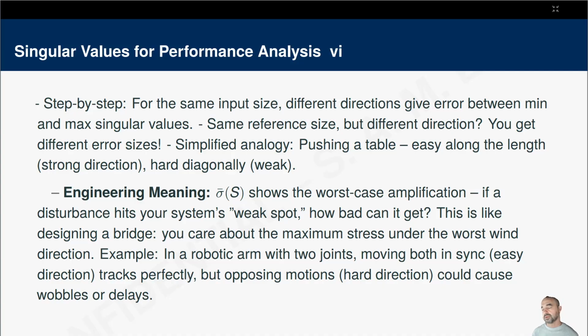In other words, think about it this way. If I consider maximum stress only on the nicest wind direction, the wind direction that is inherently gentle, rather than the one that creates maximum stress among all wind directions, I haven't really designed considering acceptable safety margins and safety criteria.